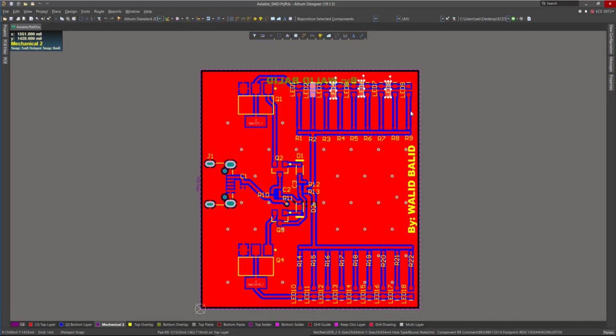Without changing the schematic, of course, try to route the board. In this case, you will need to use vias, and the board will become a little bit more complex, just a little bit, because you can solve that with the via. You have a two-layer PCB. So this is the homework. Try to do that, and you will learn a lot out of it.